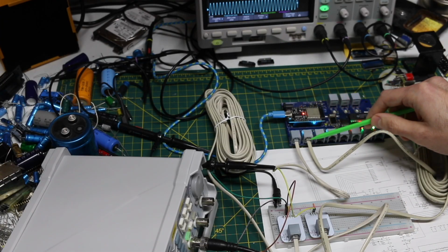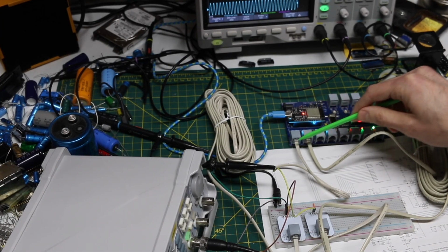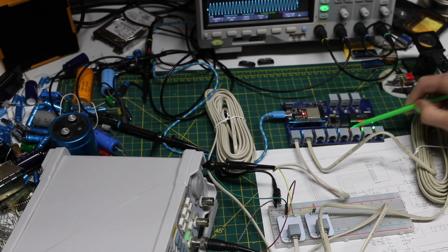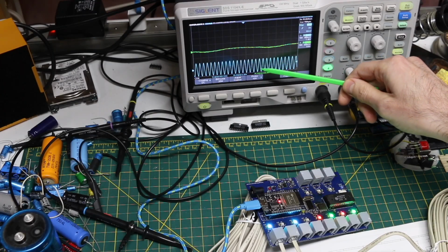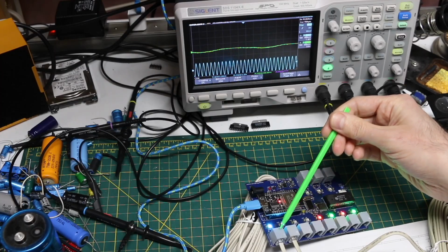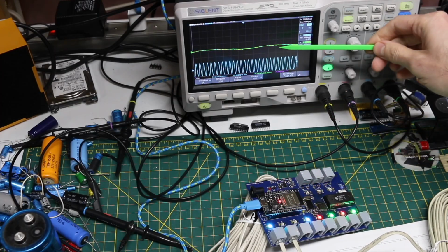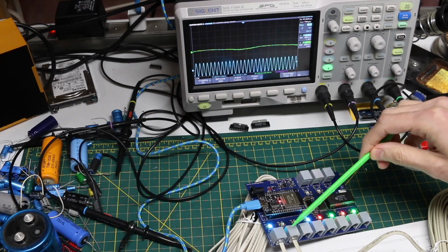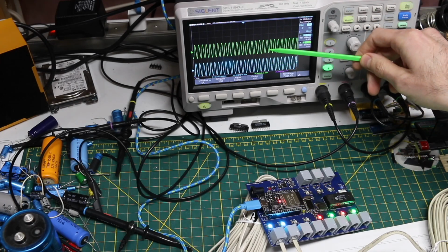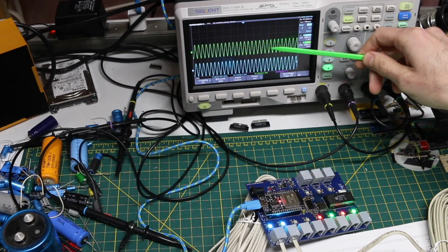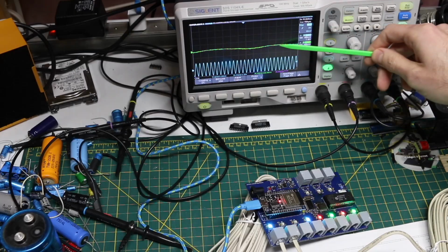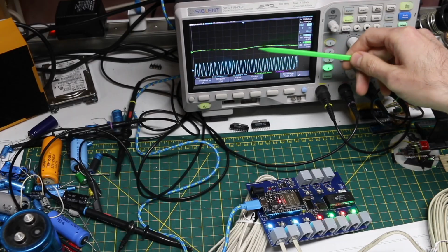And what I'm going to do is just take these cables out and move them between different jacks to see the behavior with the software I put in here. The bottom trace on the scope is the sine wave coming out of the generator, so that's what's going into the first jack on this board. The top trace is the other cable signal, so it's switching between a copy of the input sine wave and what looks like a little ripple. That's actually 60 Hz noise, so it's really just no signal or the input signal being channeled.